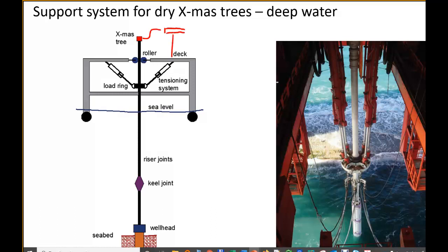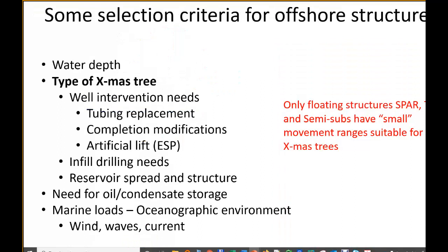Because remember, this guy is moving up and down, but this guy is fixed. We say fixed, or relatively fixed, while in this case the semi-sub is moving. And only floating structures, spars, TLPs, and semi-subs, which are not that much used, have small movements, a range suitable for dry Christmas trees. FPSOs definitely not.